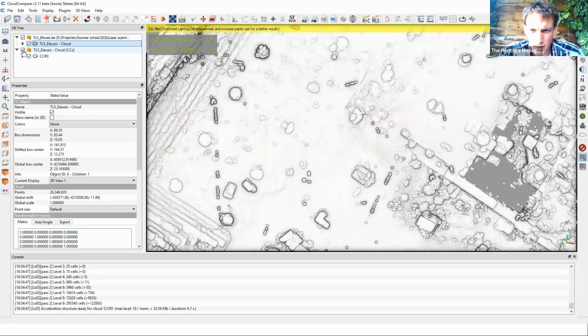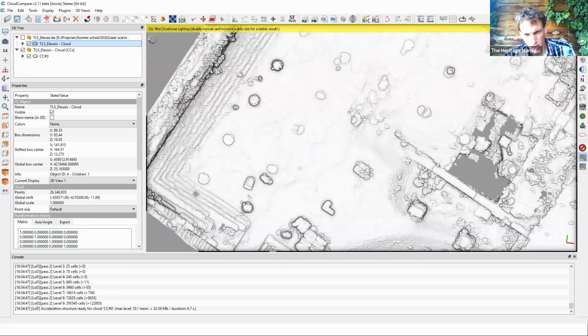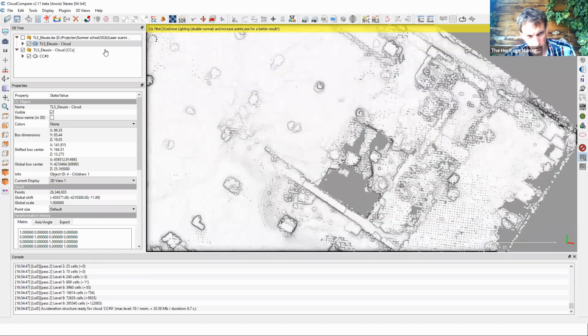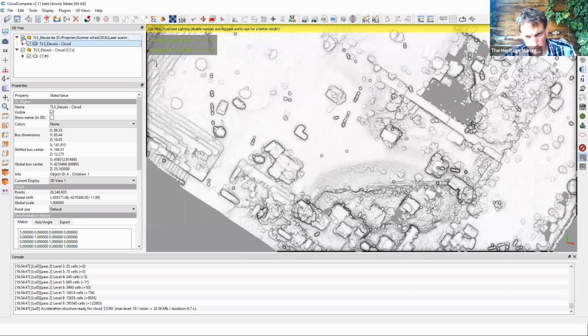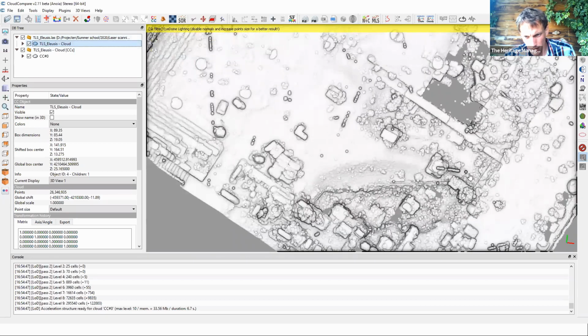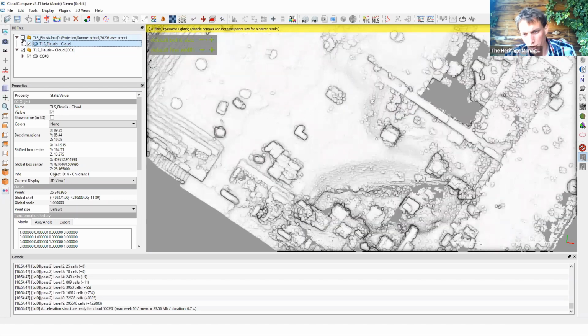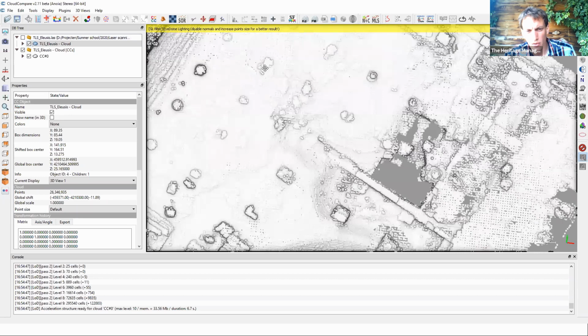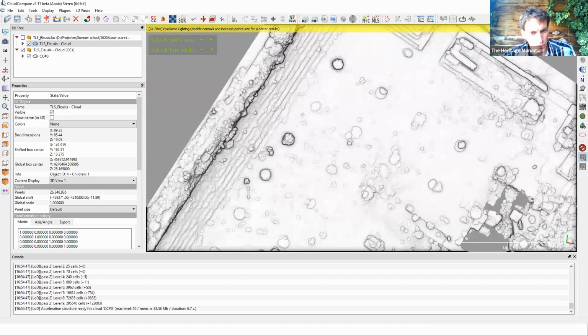And if you compare, this is my original point cloud, and this is the filtered point cloud. So you see that with just a few clicks using this connected component analysis, I've already been able to eliminate quite a few points. For example, here there were artifacts, here there are some artifacts, all these isolated groups of points that have less than 100 points in a cluster are actually eliminated now. So it's quite a convenient way of point cloud reduction.